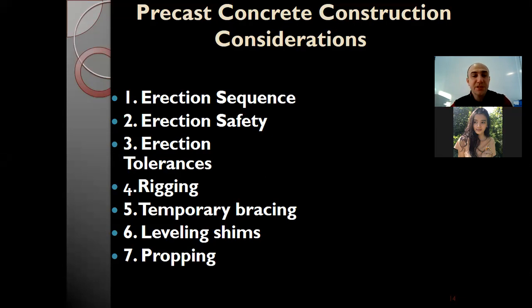Leveling shims carry the full construction load on the precast elements and must provide adequate support to prevent movement until the elements are incorporated in the main structure.